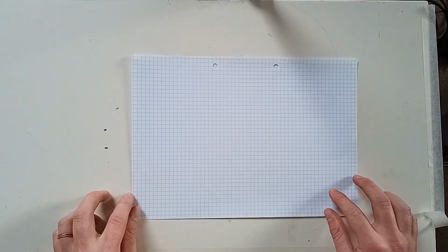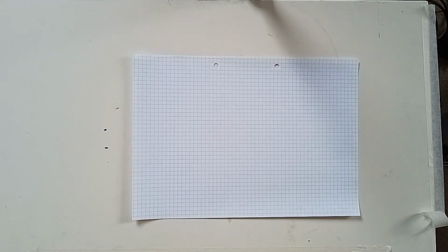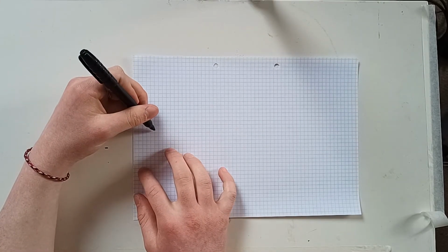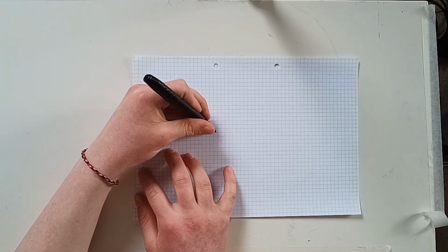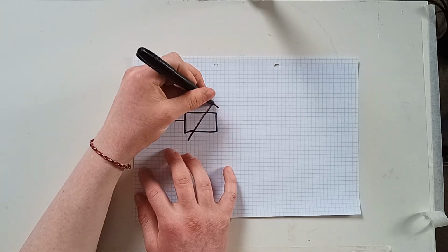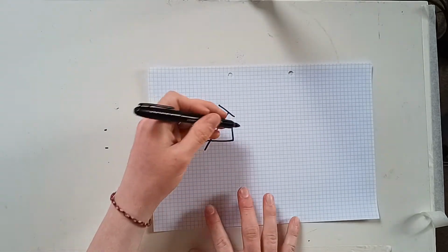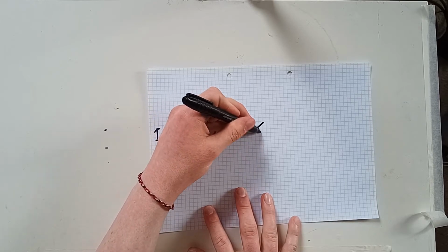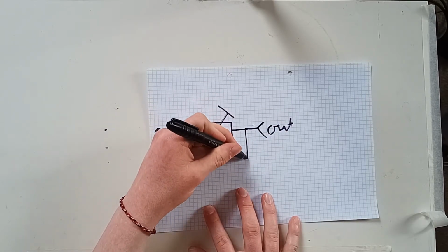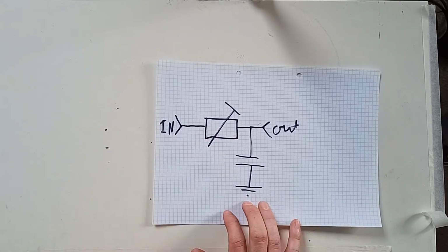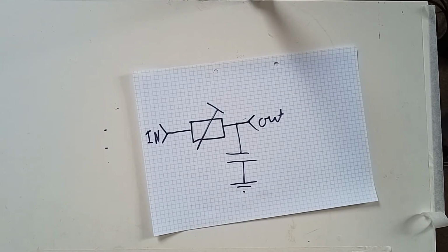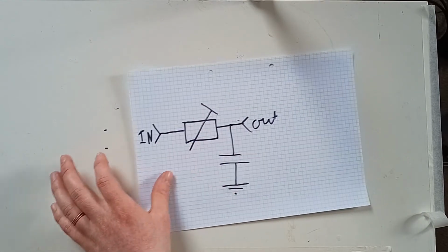But onto how you would have a variable filter. The most basic variable filter, which is passive, you would have your input signal again, which goes into a rheostat, as I mentioned earlier, which is denoted as so, going to your output with your tie-down capacitor. And tie-down just refers to it going straight to ground. And the high pass, again, would be identical, but these two are flipped.